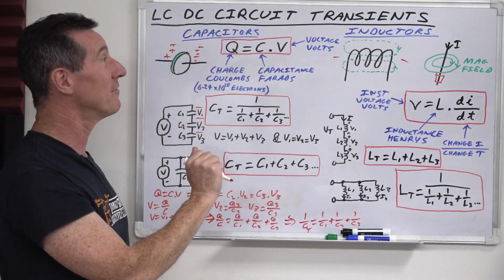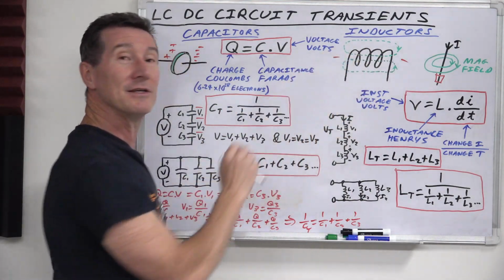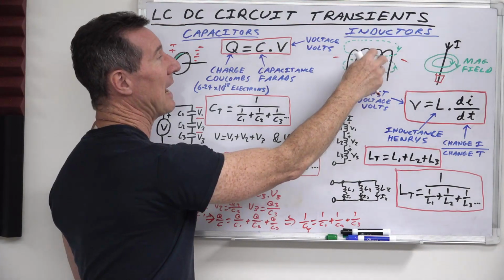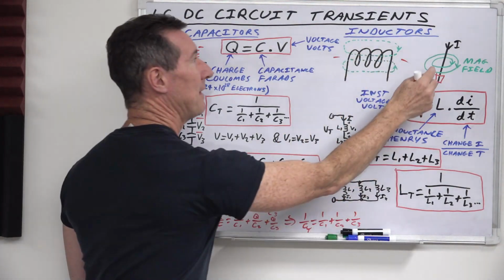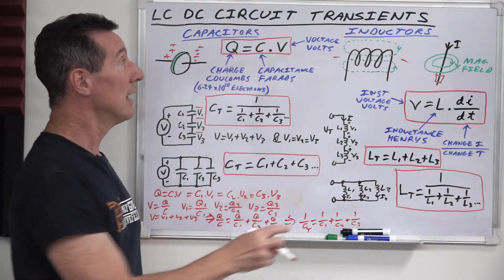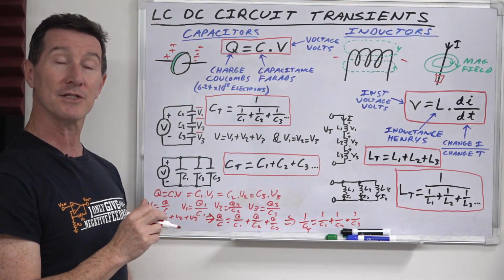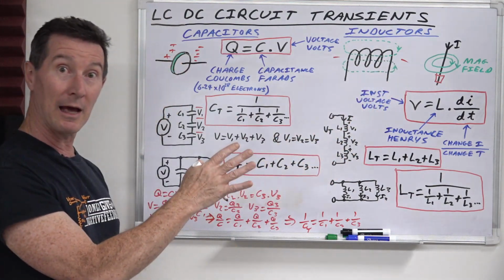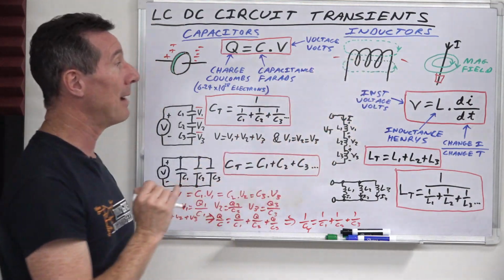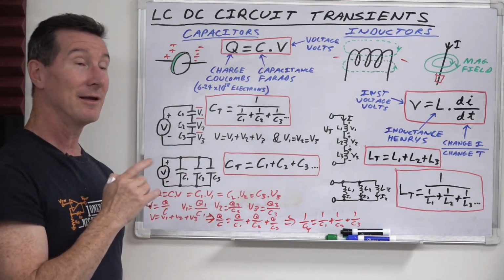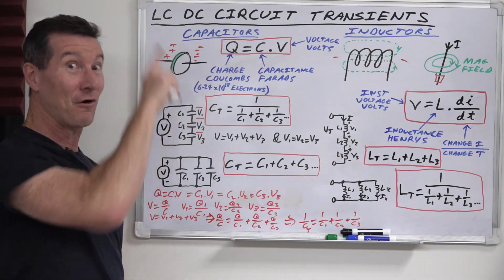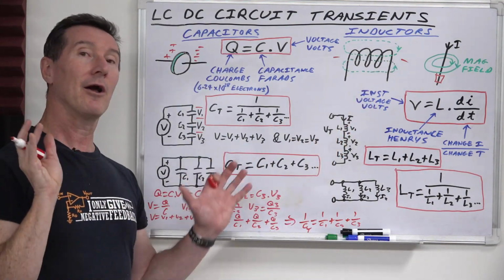That's going to have to be the subject of a future video. But yeah, inductors are more efficient when you wrap multiple turns around them. So the magnetic fields just add up in the coils, and it's much better than just a straight wire like that. So just like a capacitor, we can store energy inside the magnetic field like this. When we apply voltage to it, we'll look at how they charge up and discharge in a minute, but we can store energy in a magnetic field. When you release it, there's a few traps for young players when you release the load from the inductor. The voltage can skyrocket, we'll take a look at that in a minute. Anyway, I'm getting ahead of myself.